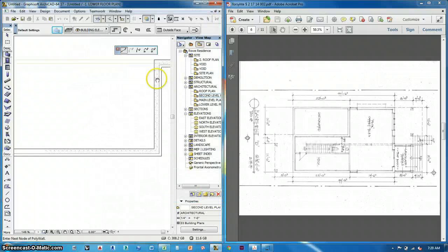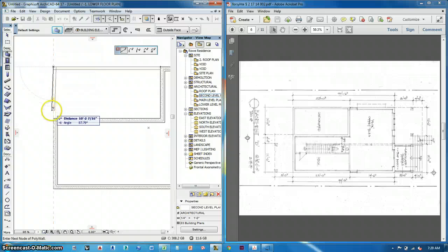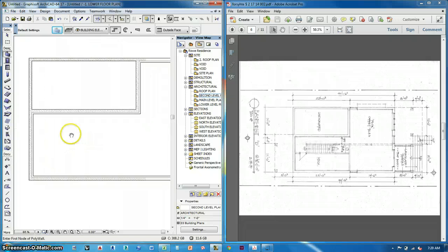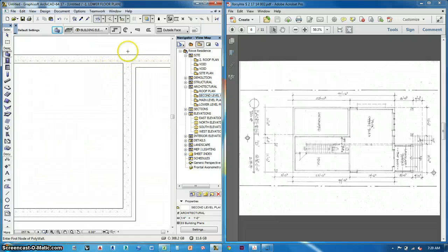And then I'm going to draw that wall right there. And you can see when I want to stop a wall, if I hit escape, everybody's done this, right? Escape, oh, my wall's gone. So what I can do is go to the end and just click that last spot one more time, and then it's done. And you can see what Archicad does. It's very smart, and it tells you, oh, this is concrete, this is concrete, so there's no line there.